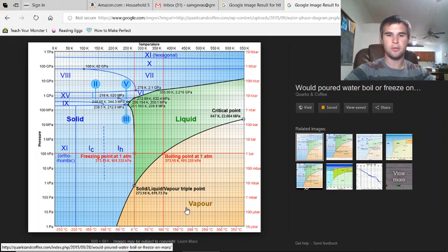Under that set point, turn the heater on. Over that set point, turn the vacuum on. Under that set point, turn the vacuum off. And just set the 2 dials, till they line up where you want them on the chart, and let the thing go. I think doing that manually would be very, very easy. But that's how you could get the controls to work.